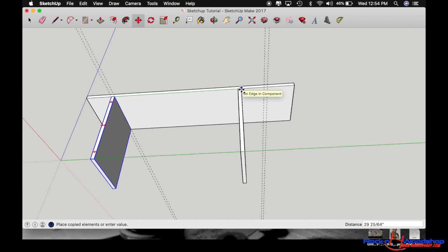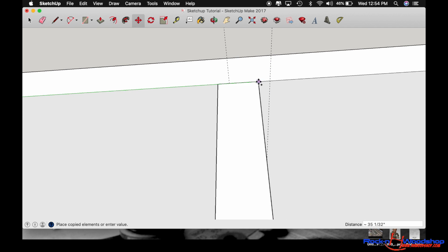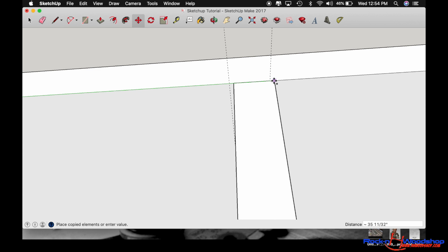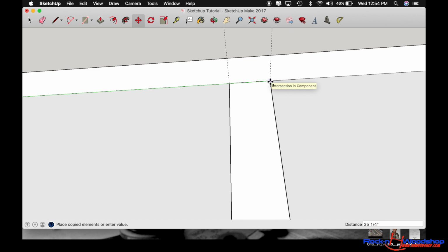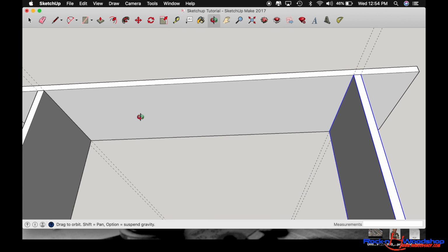And we're moving it over down here, and we're going to hover right over that reference line. And it kind of snaps into place. And then you just drop it. Now, if I was to drag from a line over here, it's very difficult to snap it into that spot, because the point you want to reference is where the corner is, because the corner is also going to intersect with these new reference lines. So like I said, remember to grab your components in an area that's easy to snap to other reference points.